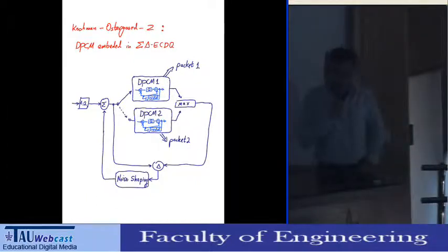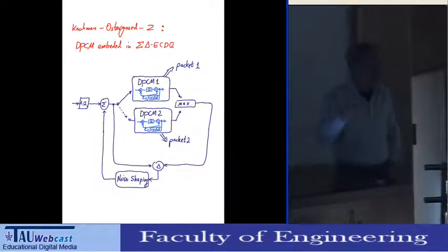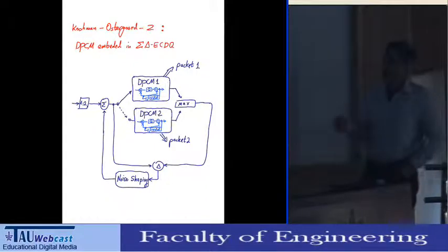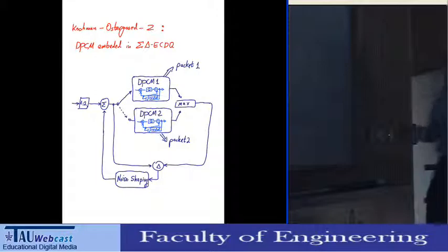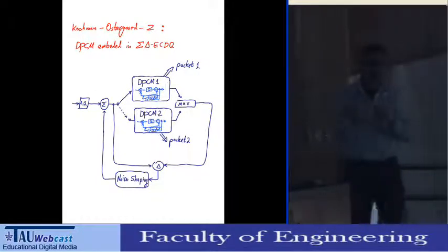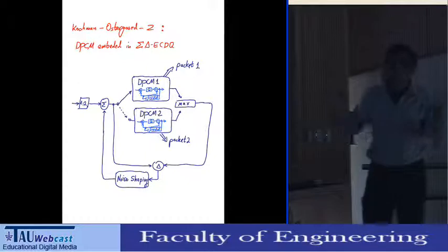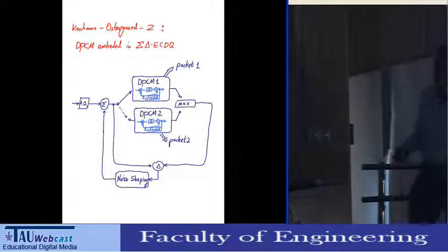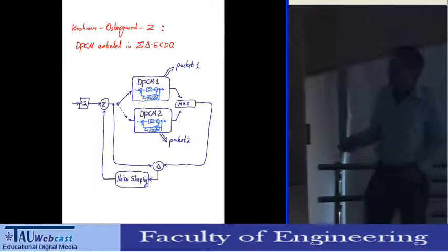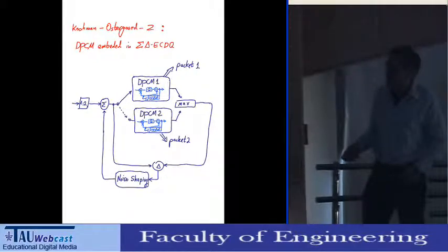Regarding memory, as we saw, the approach to sources with memory in practice is to do DPCM, differential pulse code modulation, or prediction. It turns out that it is possible to use two loops in the system. One loop is responsible for prediction. This is the DPCM loop inside here. And another loop, which is outside, is the one responsible for noise shaping. It takes the input and the output, takes the delta noise shaping and feeds it back.